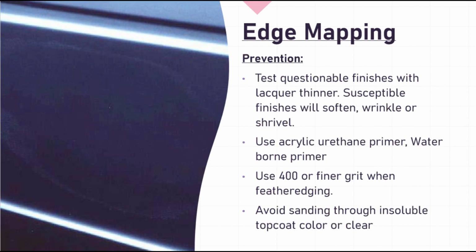To prevent edge mapping, you can test the questionable area with lacquer thinner. Susceptible finishes will soften, wrinkle, or shrivel. Use acrylic urethane primer or waterborne primer. Use 400 or finer grit when sanding. Avoid sanding through insoluble topcoat color or clear.